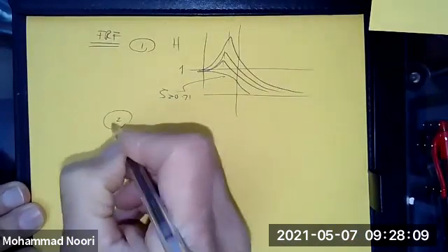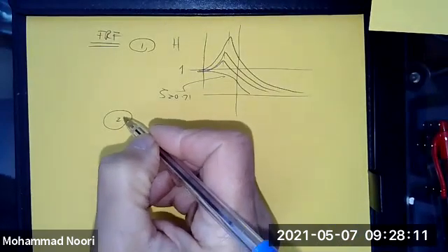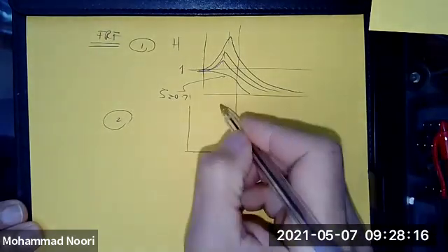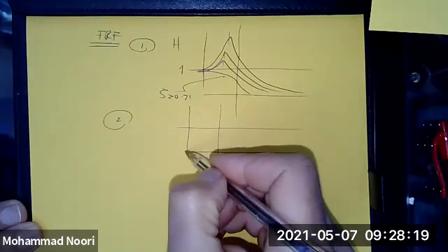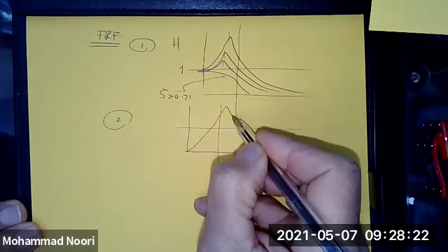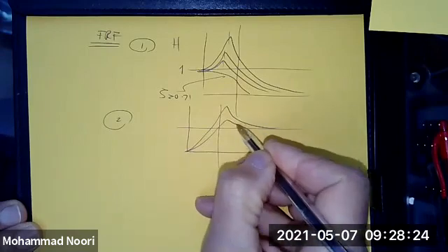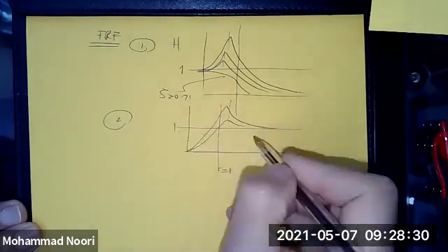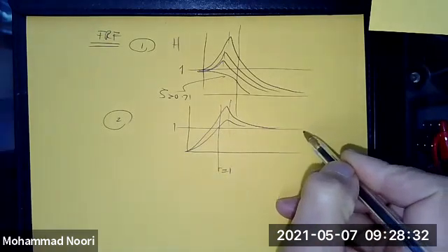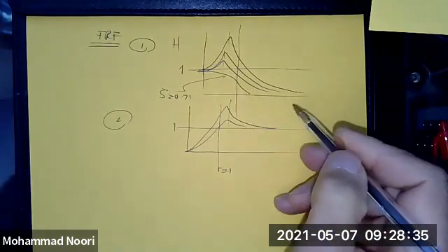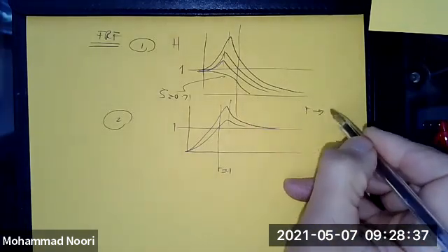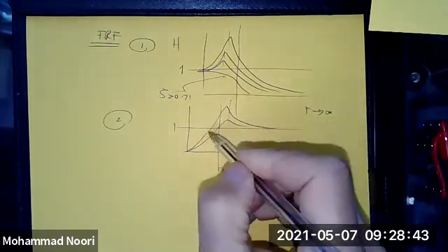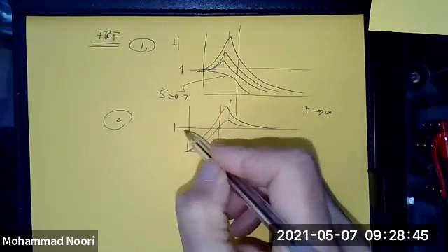If you have unbalanced rotation due to unbalance, this is the frequency response function. You will see that the shift of the peak is to the right of r equal to 1. And of course, the response when r goes to infinity will never reach zero, but in this case it reaches the static displacement.